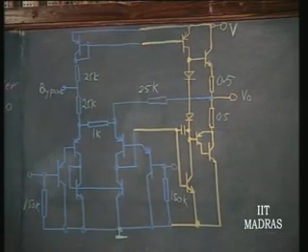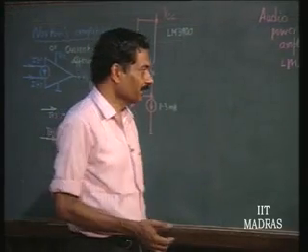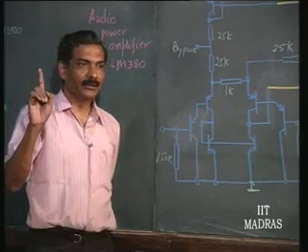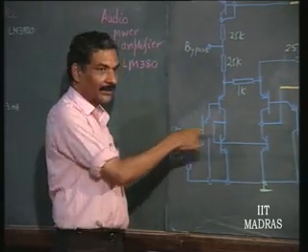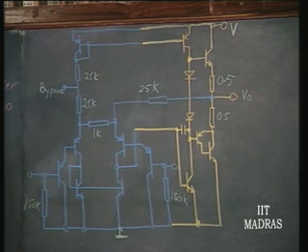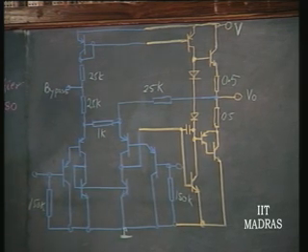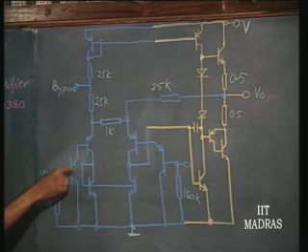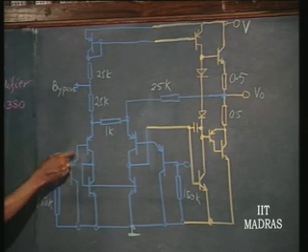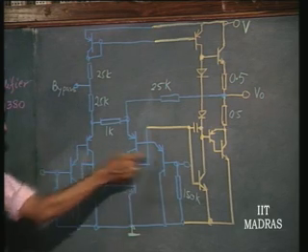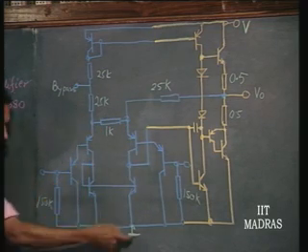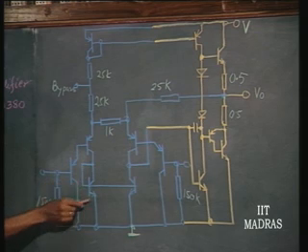So, we have to only identify the various blocks which we have earlier recognized in various amplifiers. Let us now identify the differential amplifier input stage. This operates with a single supply, and is self biased. So, single supply self biased audio power amplifier is what we are going to discuss now. This is the input stage. You can see here the buffer stage. These two will be acting as the buffer, and the primary pair is here, and this particular thing is nothing but the active load. You can see the diode here getting reflected.